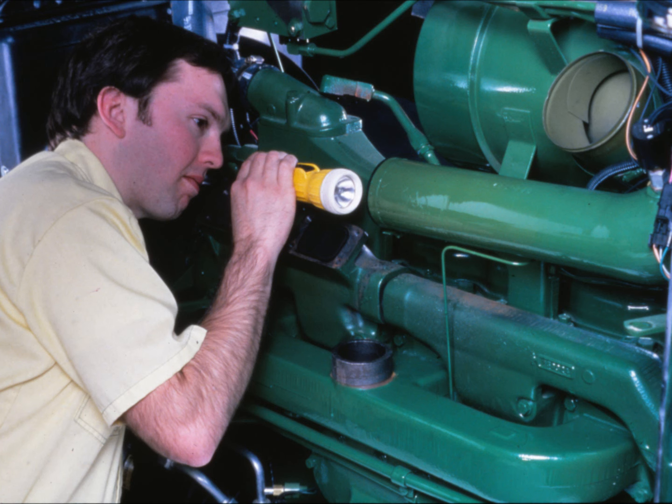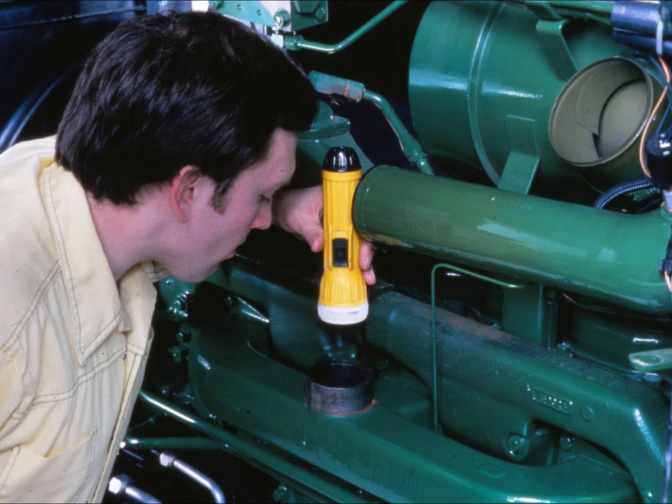Foreign object damage to the compressor wheel requires extensive inspection of the air intake system. Often the foreign object is ejected back into the intake system. If it is not found and removed, it will fail a replacement turbocharger. Foreign object damage to the compressor wheel also requires inspection of the intake manifold. If the engine is not intercooled and a foreign object has passed through the intake system, the cylinder head should be removed for inspection of the engine. If the engine is intercooled, the top of the intercooler core should be inspected. Debris will collect here, but generally will not enter the engine.